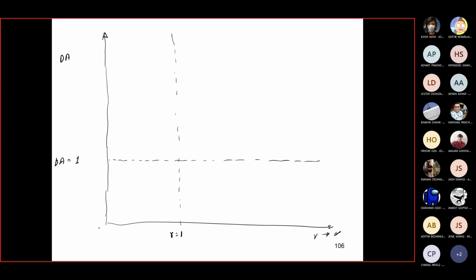All right. So let's start with the most critical curve, that is when zeta is equal to 0. So when zeta is equal to 0, this dimensionless amplitude goes to infinity at resonance. Okay, and then this curve will come down and will die out at dA equal to 1. And as long as zeta is less than 1 by root 2, you will observe peaks.